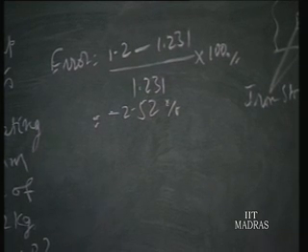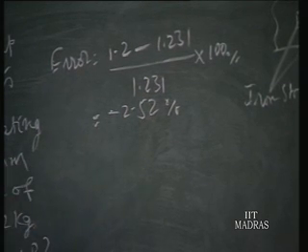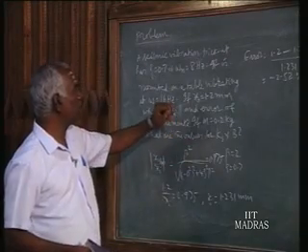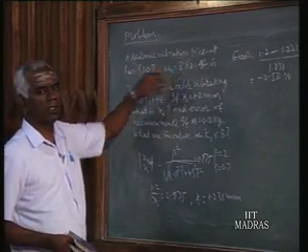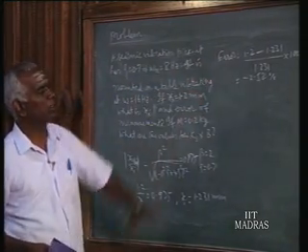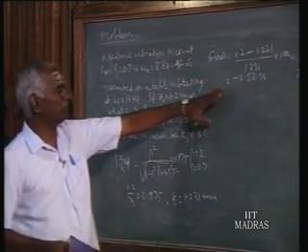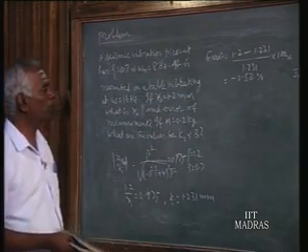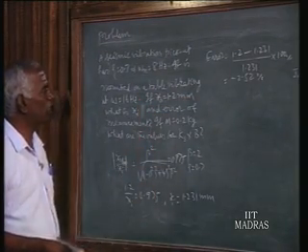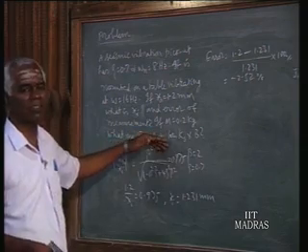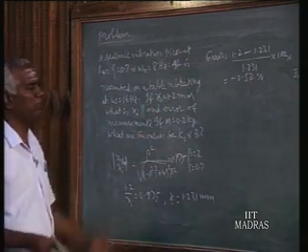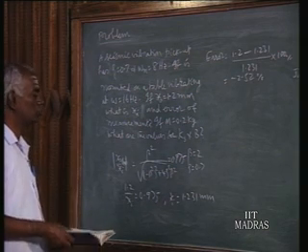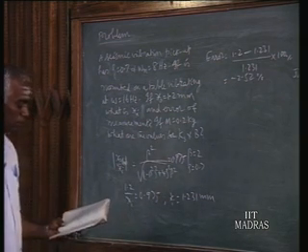So we see that within the allowable limit we are able to measure with this seismic absolute displacement measurement, provided the vibration frequency is much larger than the natural frequency. Here the ratio is 2, so it is giving a result within that error zone. Say plus or minus 3 is acceptable. So minus 2.52. Since the vibrating frequency is large, Xo becomes more or less the same as Xi. That is what we demonstrated, which we saw previously. Physically we saw that it should happen like that. So this is a demonstration.